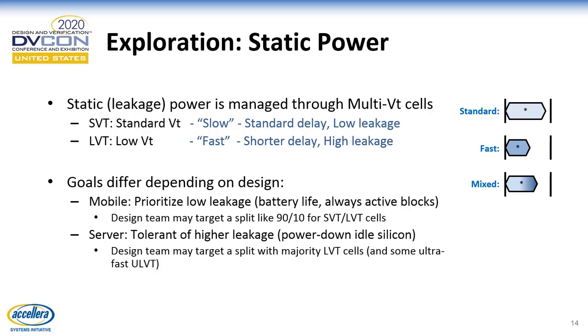Rough idea, if you're a server, you might be tolerant of higher leakage. Often you will be able to power down certain power planes when you're idle. You have more tricks to play. If you're mobile, though, you often are always listening or always on, depending on the function of the chip. And when this is the case, you can't really save that leakage power by powering down. You need to be ready to go. So when it comes to a mobile design, we're really looking to minimize any of these high leakage cells.